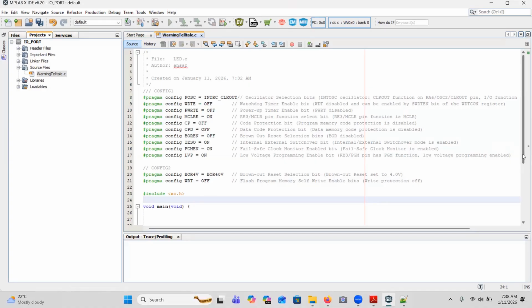It is actually these on-off configuration registers. They have a memory location, right? That memory location doesn't have a physical register. So when you set these values, it will automatically go and set the flags in the memory of the microcontroller. Right. For a detailed description of these settings, I believe it is part of the datasheet. It should be there in the datasheet.